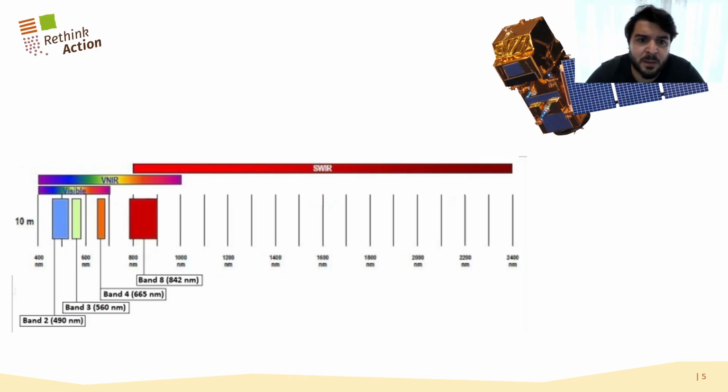The idea here is to enhance our classification. We calculated several spectral indices from each of the quarters. We use NDVI, a common and standard remote sensing index, which stands for Normalized Difference Vegetation Index, for measuring vegetation health.